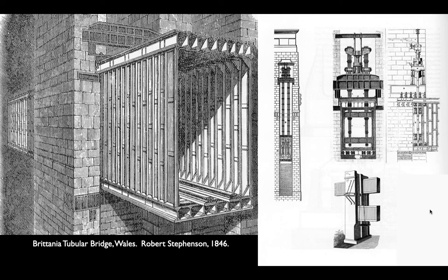It's a double web beam, and the flanges, top and bottom, are essentially doing the same thing that a flange in an I-beam does, right? So this is just a great big I-beam, but with the web split so that there's room for a train to go through it. You can see on a kind of micro scale, he takes the same principle, right? So those two flanges are actually made of little I-beams that are bolted together.